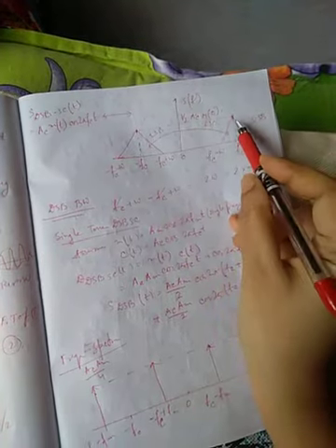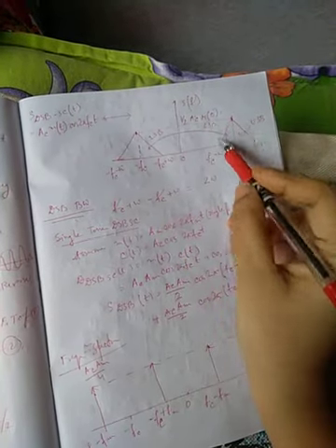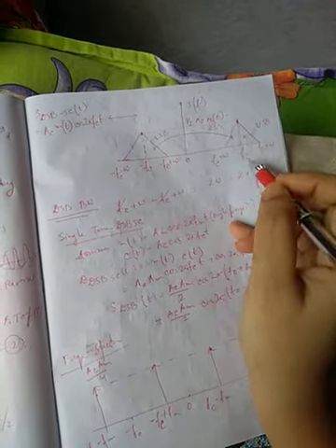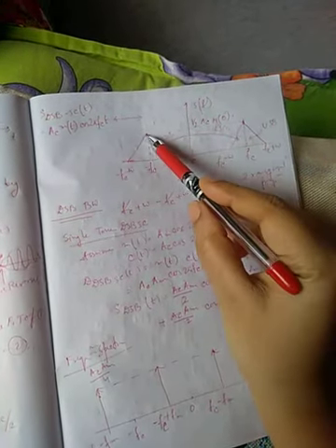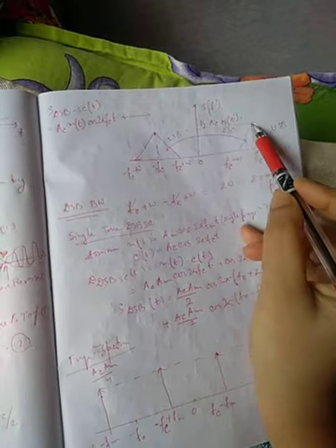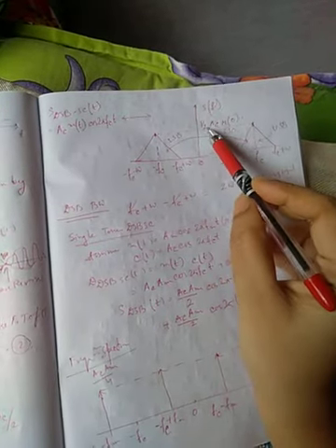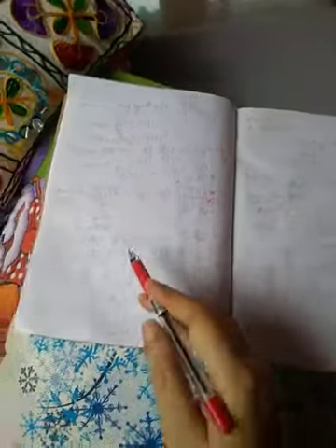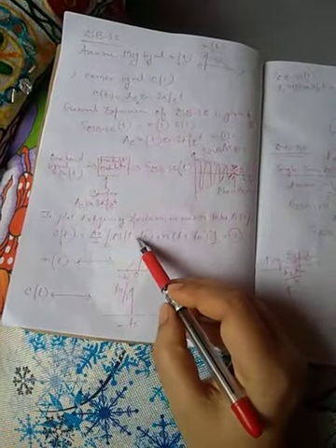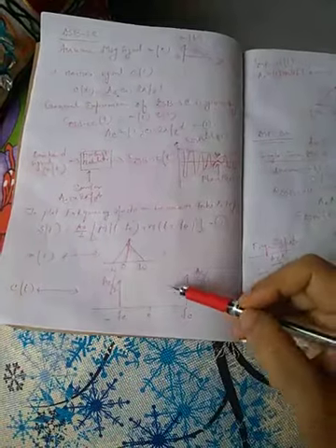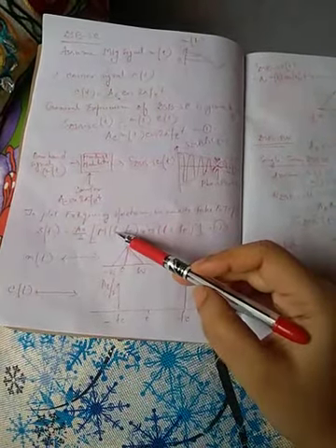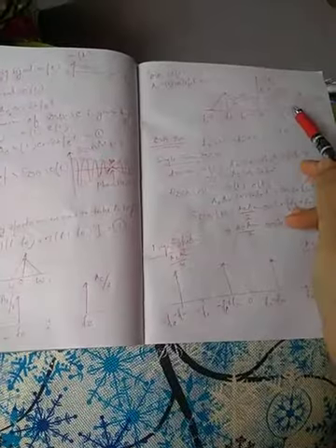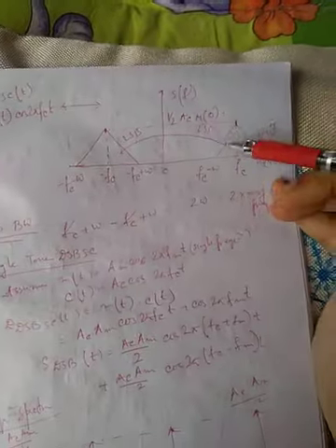I have made fc a dotted line to show that the carrier is suppressed here, and the size of the envelope is half of Ac times M(0). If we take f equal to fc, then f minus fc equals 0, so the height is Ac/2 M(0).